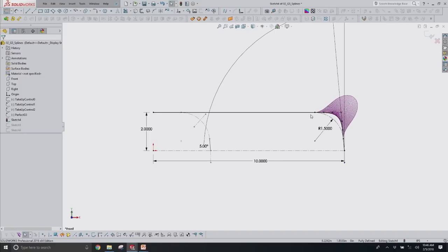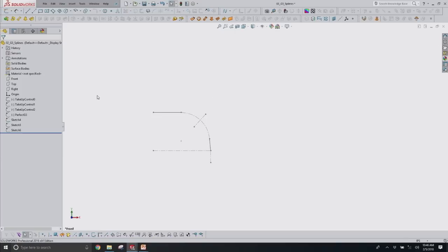But sometimes the points don't move, but there's a fix. If they don't move, all you've got to do is just exit the sketch. This will all be red and yellow, look like ketchup and mustard, but just exit the sketch and do a Control Q rebuild, and that should wake it up, and the points should move.